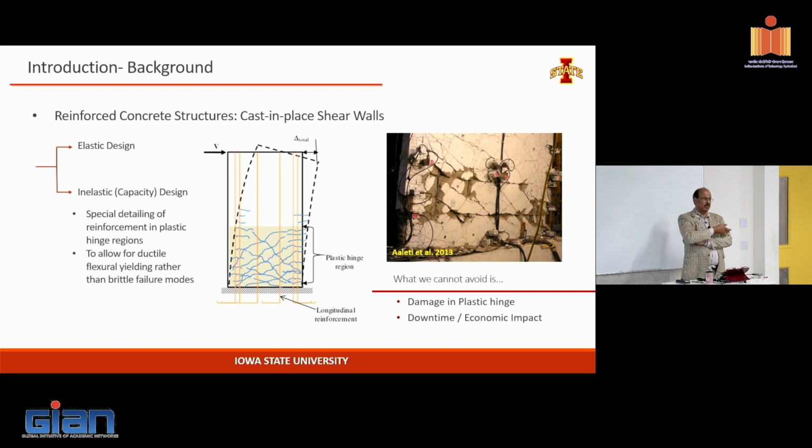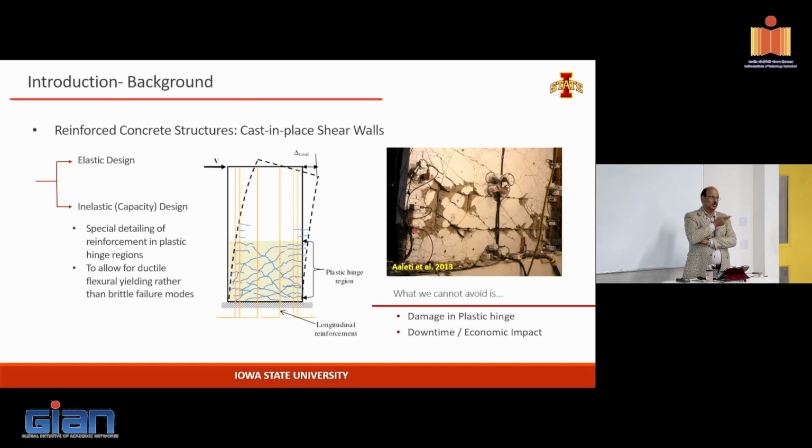With the controlled rocking, the question is how much post-tensioning you want to put in, and then how much energy dissipation you want to put in. Those questions remain to be answered. The amount of post-tensioning is typically done fairly easily because the moment resistance will dictate it. The amount of post-tensioning steel depends on what initial stress you want to maintain, and we will talk about it a little bit more later.